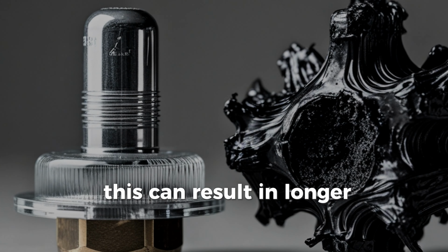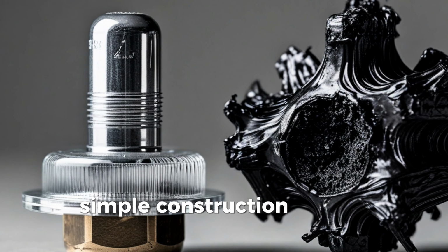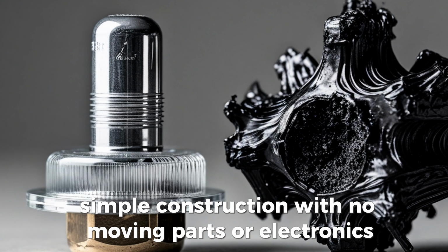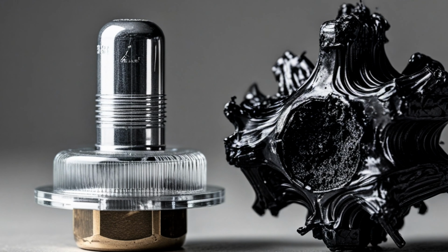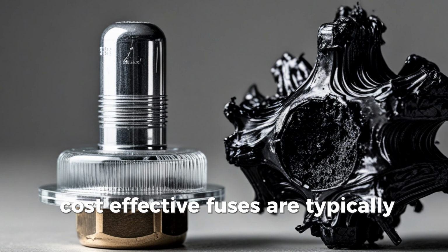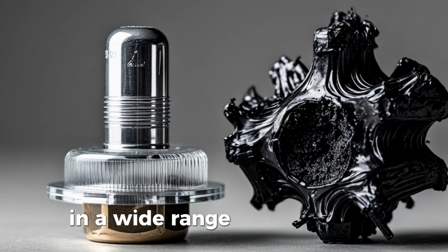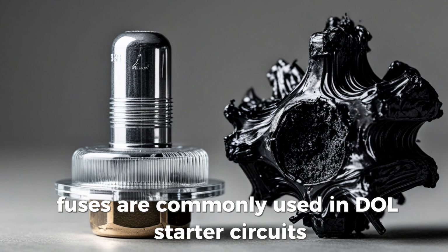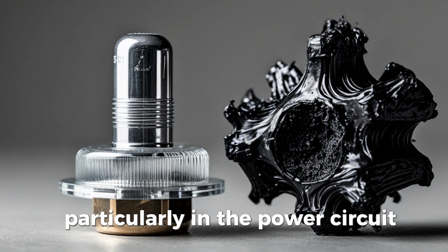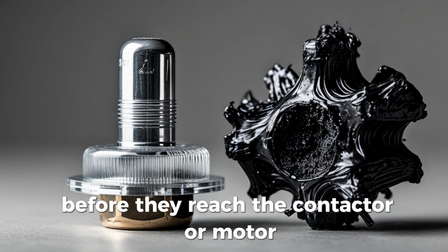This can result in longer downtime if spares aren't readily available. Simple construction. With no moving parts or electronics, fuses are extremely reliable and resistant to mechanical wear. Cost-effective. Fuses are typically inexpensive, making them suitable for low-cost protection in a wide range of applications. Fuses are commonly used in DOL starter circuits, particularly in the power circuit, to provide primary protection against faults before they reach the contactor or motor.